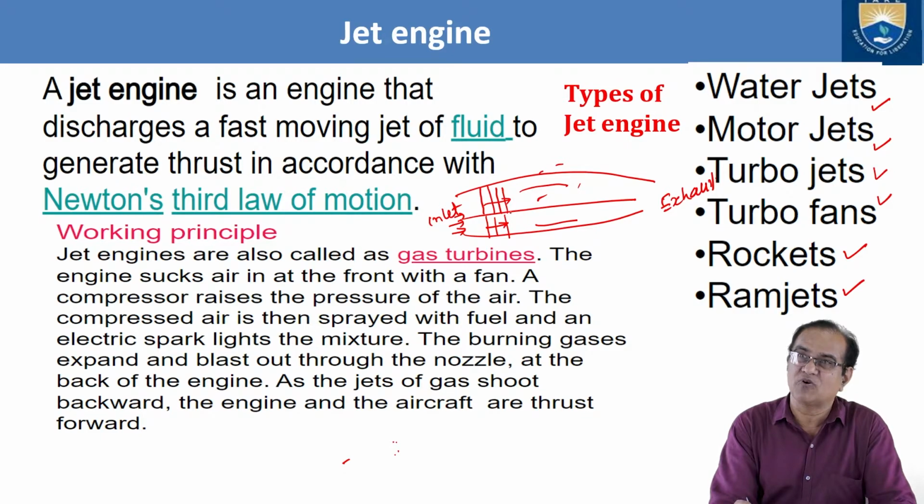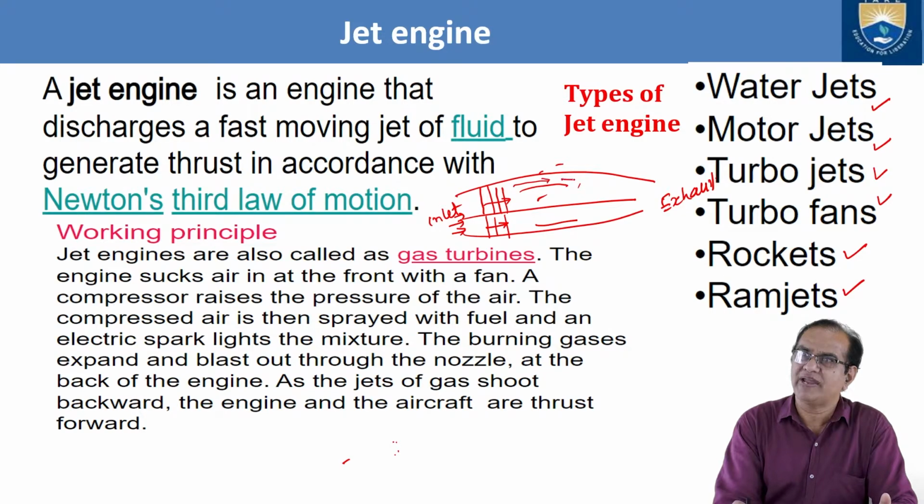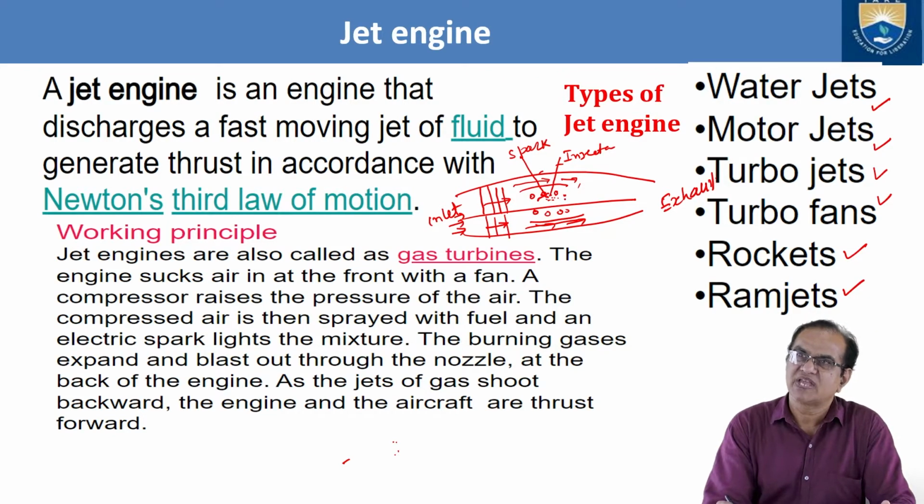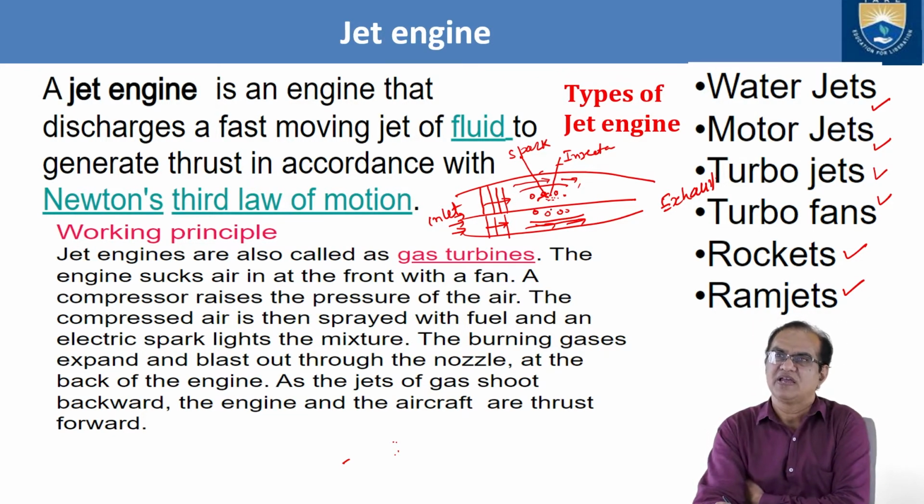The topic is air flow, so we have to understand that. Some airflow will move above and it is not taking part in the burning. So only 30 to 40% of the air is used here in the combustion chamber, and from the injector, fuel is sprayed here, and from here one spark is used to ignite the system, and this will burn.